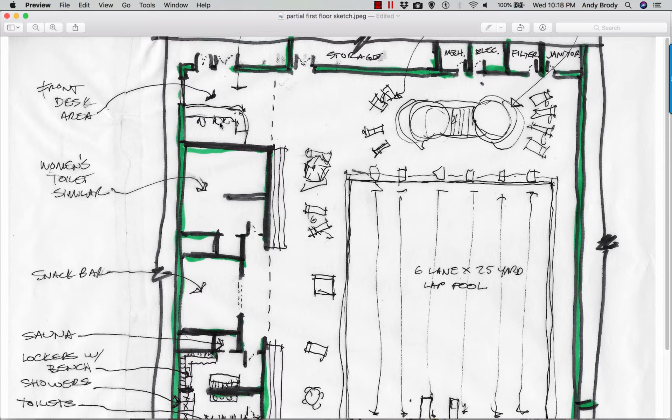So anyway, the other purpose of these schematic plans, the first stage of design, is that you want to develop some three-dimensional sense of what the project looks like, and then you want to, in a general sense, identify the scope and intent of the project. For example, where is the limit of construction or the limit of work?